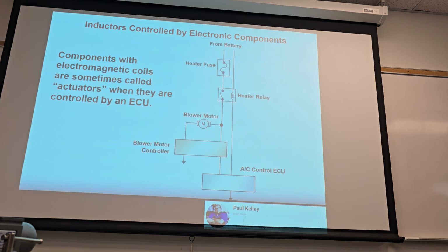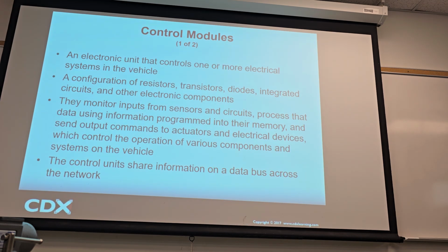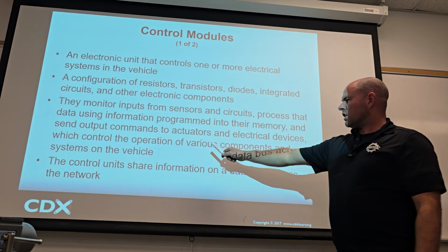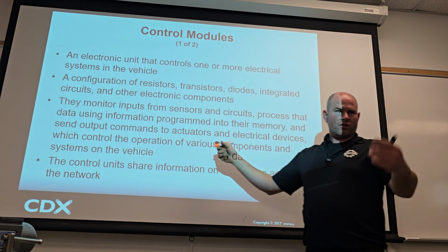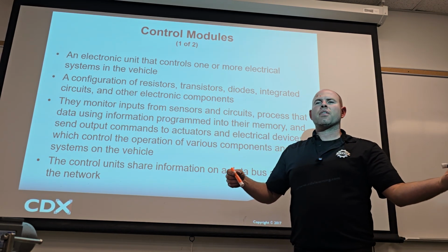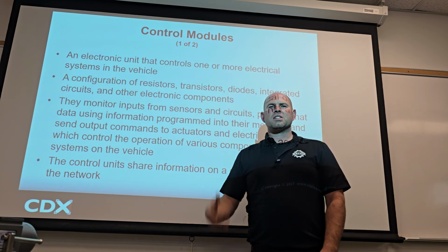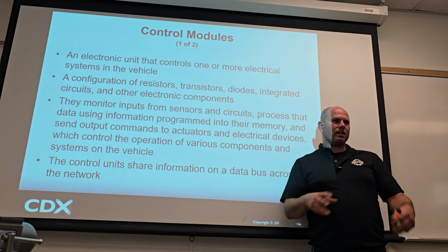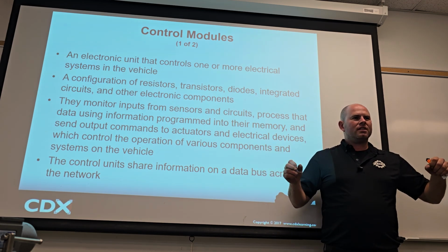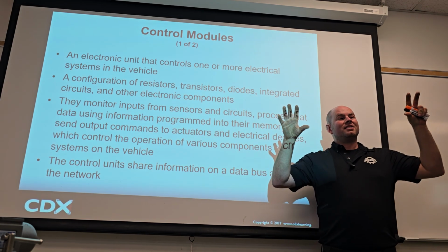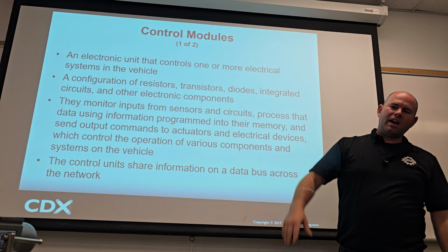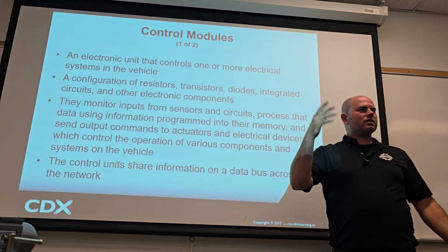How'd that feel? It hurt you a little bit? It's okay. You can take it. All right. So if it's going to control various components, for example, the motor, it could control other things. It could also say, hey, it just got dark outside. What should it do if it just got dark outside and it's that body control module? Turn the lights on. It can control those too. It can be like turn on the lights, turn down the AC.